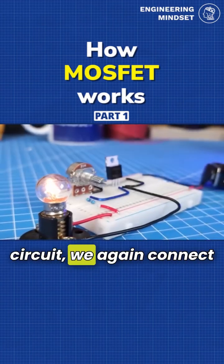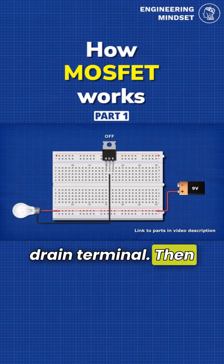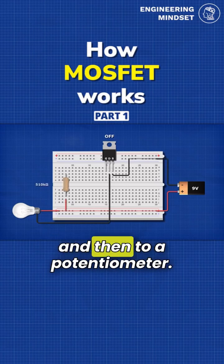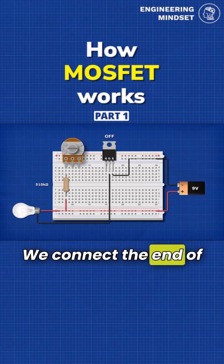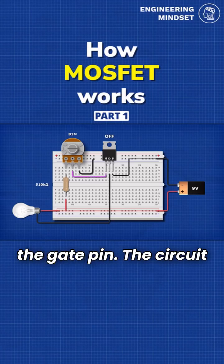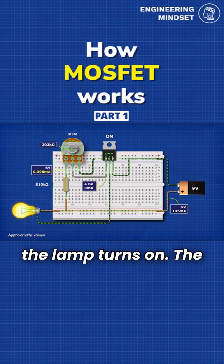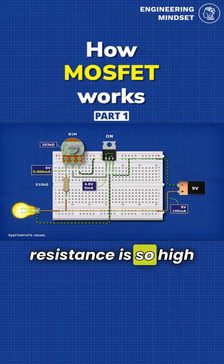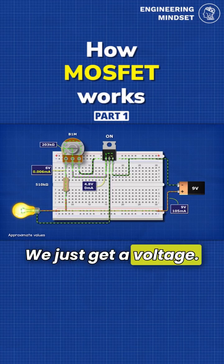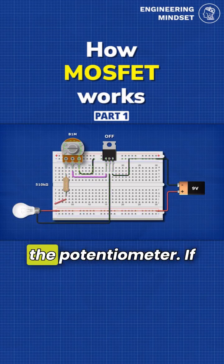For the next circuit, we again connect the 9-volt battery to the lamp, and then the lamp connects to the drain terminal. Then we connect the source to ground. Then we connect the battery to a resistor, and then to a potentiometer. We connect the end of the potentiometer to ground, and we connect the center terminal to the gate pin. The circuit should look something like this. The MOSFET will be activated, so the lamp turns on. The resistance is so high here that almost no current flows through the resistor. We just get a voltage. When we disconnect the power to the resistor, the MOSFET drains through the potentiometer.